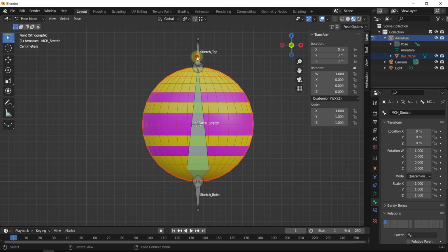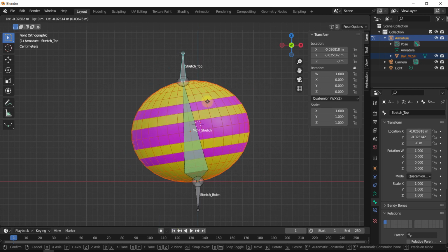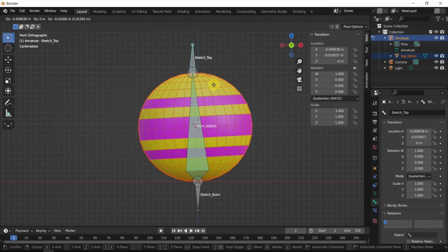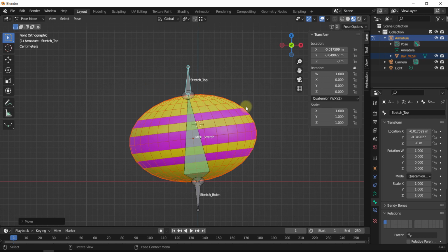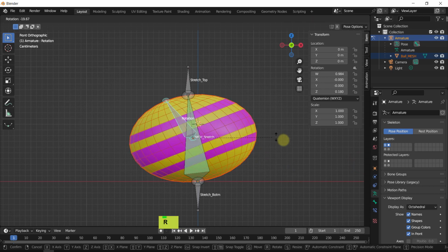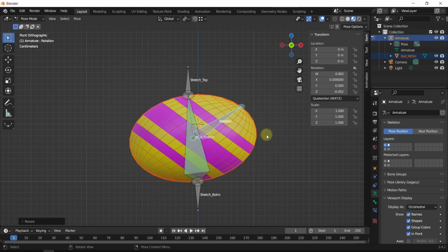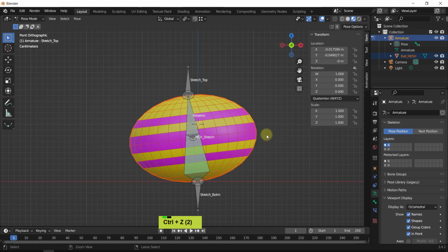So now on, if I'm selecting this in pose mode and I'm pressing G and move it away, this is what happens. And because this stretching is coming through a set, let me just turn back on the stick figure, and turn on the layer. We have rotation, and if I'm selecting rotation and start rotate, I can still rotate, and this whole stretch is maintained. Okay, so that's the goal of it. Let me undo this and go back in position.